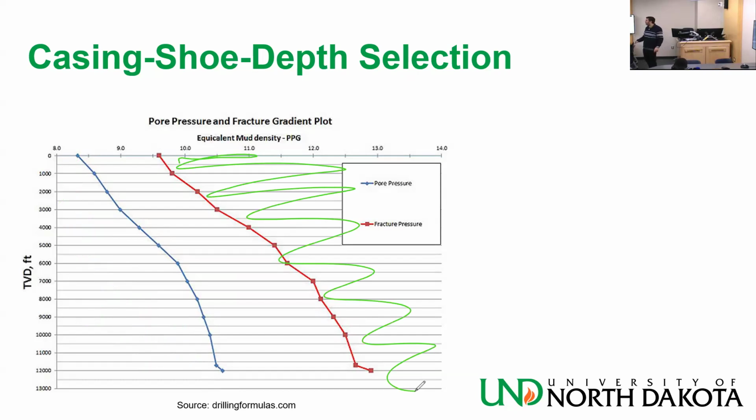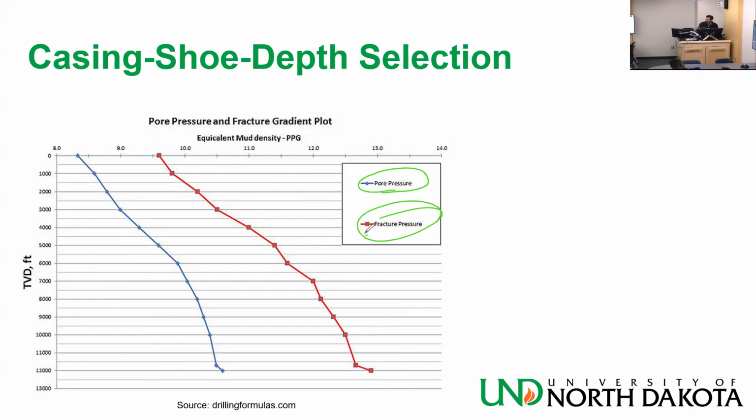Okay, you are gonna fracture the rock, and then you are gonna lose mud through the rock. When you lose mud through the rock, you are gonna remove mud from inside your well. The pressure will go down, and basically it's gonna be as if you are here, and you are gonna get a kick for different reasons now, because you lost your mud. That's when you have lost circulation. Okay, now pore pressure and fracture pressure are terms that are very, very loose, especially the second one, the fracture pressure. Because as you saw when we did geomechanics, fracture pressure can have 2, 3 different values, and you need to choose the smaller one, right?